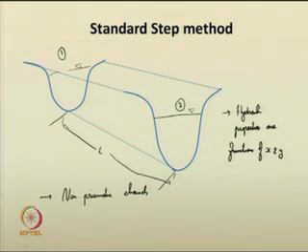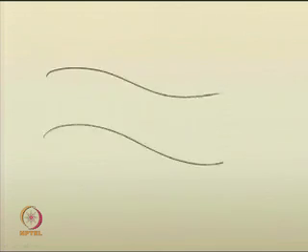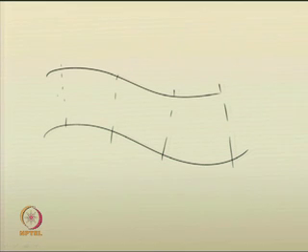In prismatic channels we have seen that most of the properties are functions of only the depth of flow y, but that is not the case in non-prismatic channels. So, we have to account for this. Say you have a reach of a non-prismatic channel, they may conduct various field surveys at various locations, both cross sectional surveys and longitudinal surveys along the reach, and the cross sectional details will be captured at various locations.